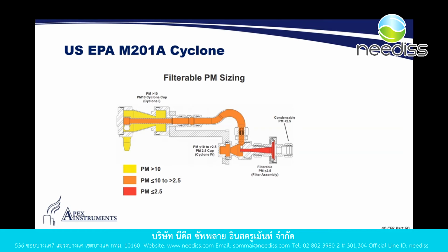And what condensable PM is, it is particulate when in its hot, maybe wet phase inside the stack, acts and looks like a liquid. It looks like moisture in the stack. But once that particular particulate enters into ambient air, it actually turns into a solid.